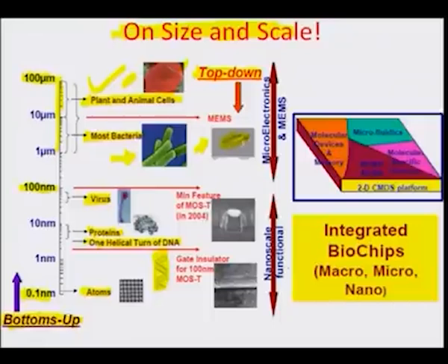The reason why I am illustrating all this is that some of these features and structures rhyme very well size-wise with these biological entities. For example, this is another very interesting example. It is a polysilicon gate with nitride spacing, and the minimum feature size of a MOS transistor, which has been declared by the ITRS roadmap in the year 2004, is less than 100 nanometers.